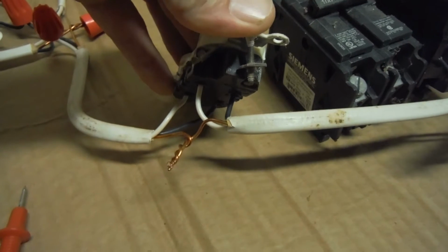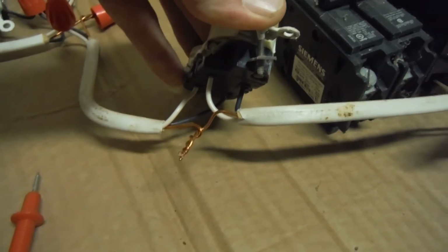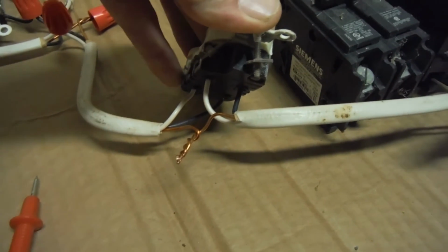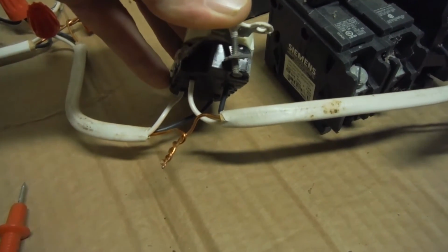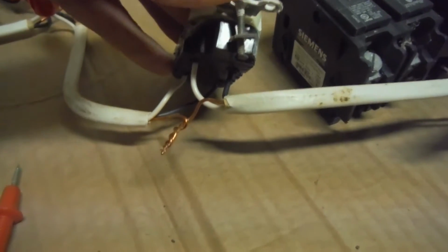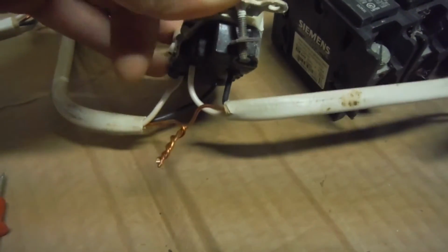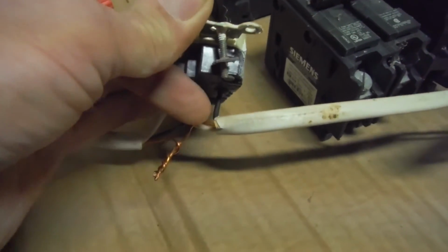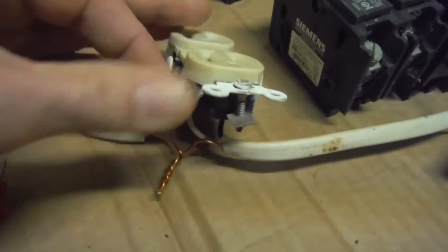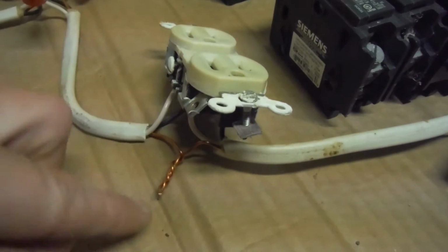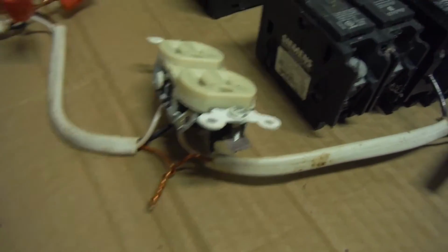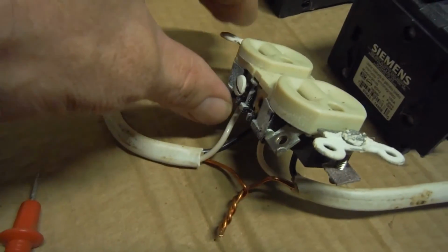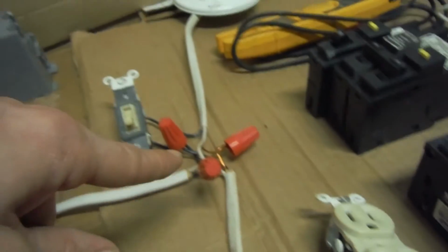And this is a 110 normal, regular, everyday circuit that says bedroom, or living room, or dining room, or something like that. I'm not talking about your stove connection or anything like that, but normally it comes in, you can see you got your white line coming in, your hot line coming in right over there, your ground normally is attached right here. I don't even have a screw, so I just kind of twisted it together. Sometimes it's done like that, but then it comes out. Exact same thing, white out of white, black out of black, and continues on.